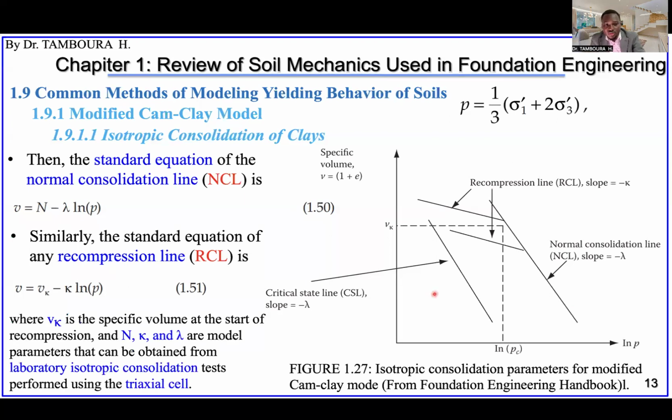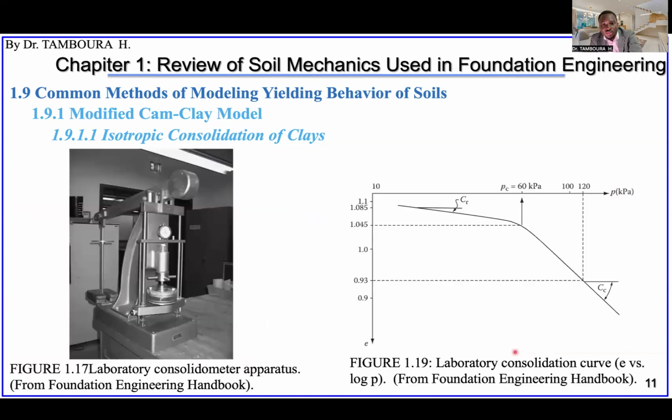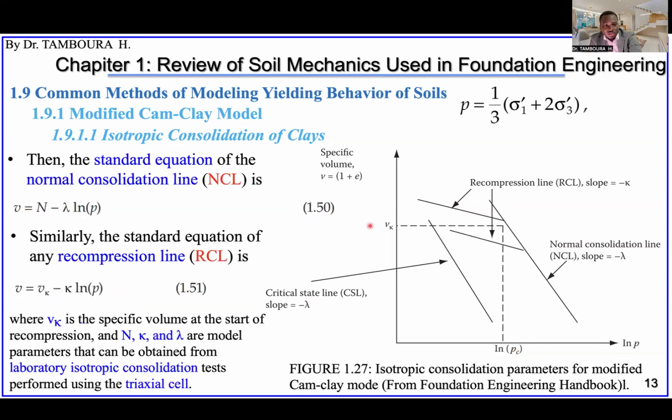Okay, so this VK here, corresponding to this PC, let me go back a little bit to show you. It is like here, this P, the maximum load that the soil has already experienced, and the corresponding void ratio. Okay, so let's go back. Vk here is the specific volume at the start of the recompression here.